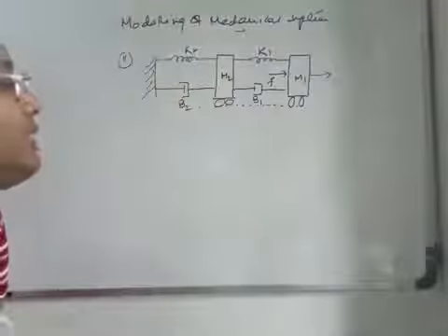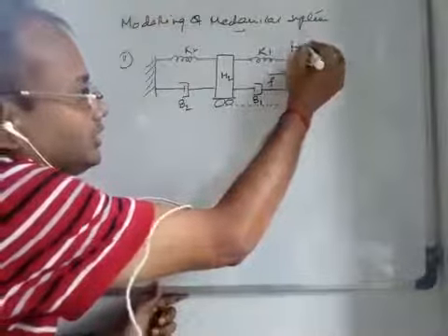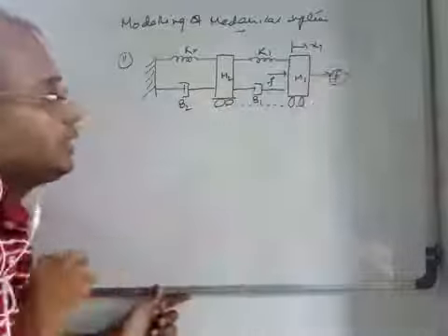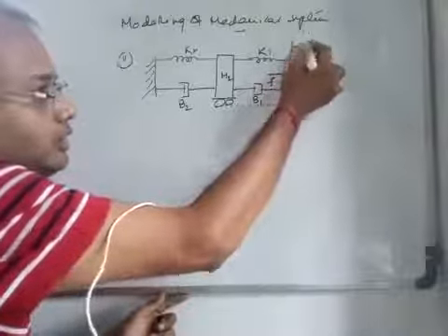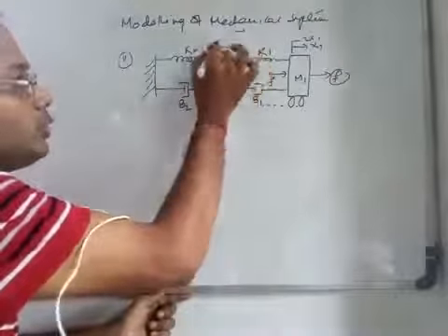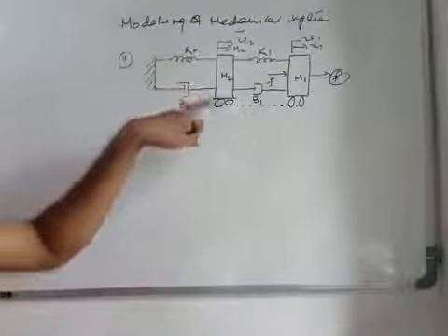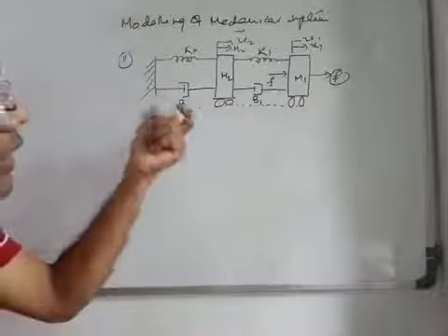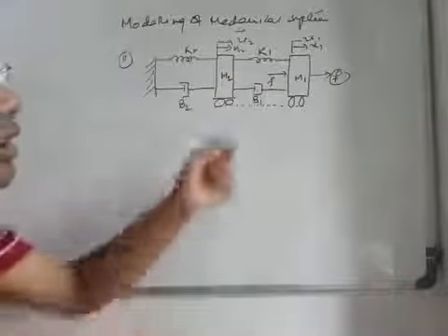So basically, when this type of system is given to you, you have to identify the displacement of each mass. Say if you apply force F here, or a similar force here also, you get the same kind of response. So this is x1 corresponding to velocity v1, and this mass moves x2 corresponding to velocity v2, right? So first of all, again like the previous mathematical modeling of the system, you have to draw the free body diagram corresponding to masses m1 and m2.